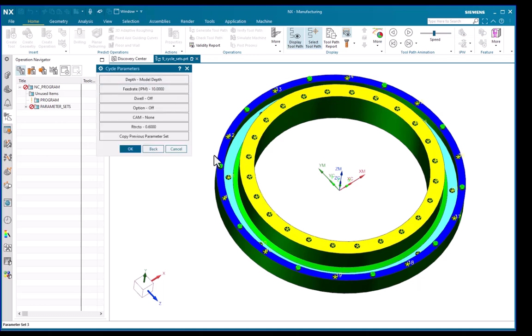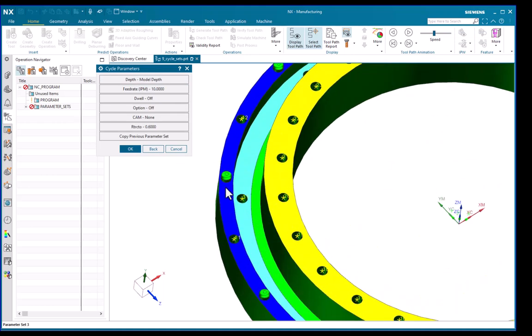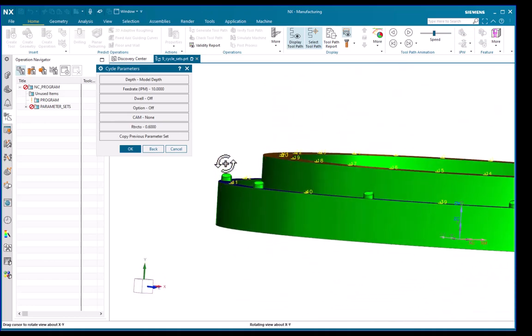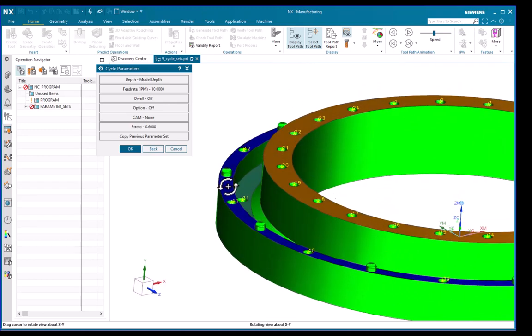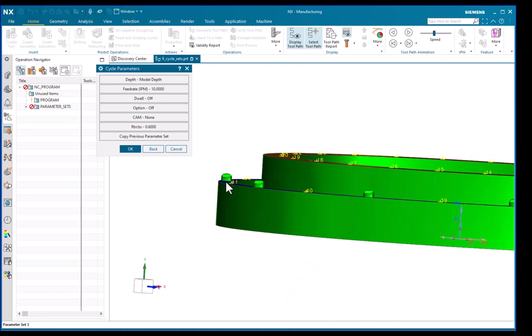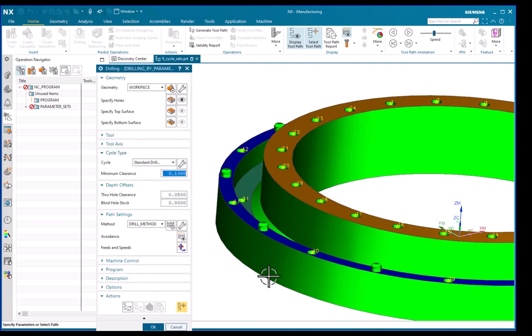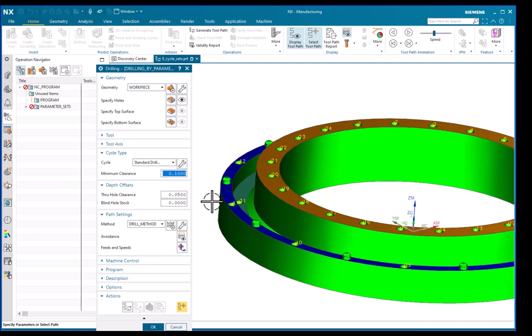The reason behind giving the retraction value of 0.6 is this face, that is the dark blue face, has screw heads that have a height of 0.5. So these are the screw heads which have been arranged here alternatively, whose height is 0.5 above the surface of the layer. Therefore, better we give the retraction value of 0.6 here, otherwise the tool may collide with the part again. So click OK. In this way we have defined the cycle parameters for all the cycle parameter sets.